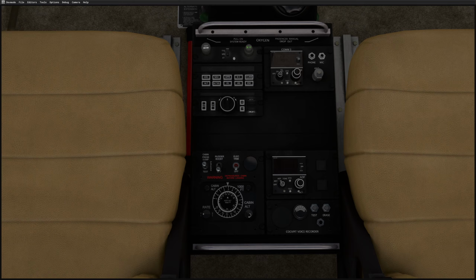But there is a limit to how high we can fly. If the difference of pressure between the actual outside air pressure and the inside cabin pressure is too great, it can cause failures, structural failures. It can cause a leak. So this tells you the maximum altitude you can fly at if you want to maintain this level within the cabin. So we do need to select that wisely depending on which altitude we're going to fly at.